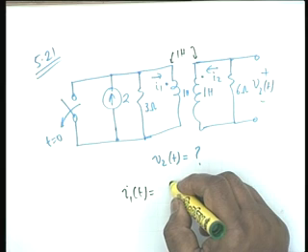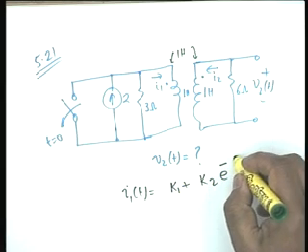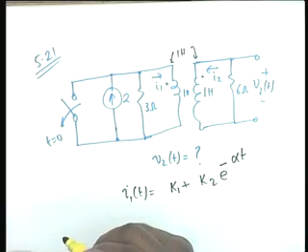But what do you think will be the order of the circuit? What order do you expect? I think we have done this, that if L1 L2 is equal to M squared, then it becomes a first order circuit. Okay. So if one asks you, without calculating anything, can you write the form of I1(t) and I2(t)? Obviously it will be of the form k1 plus k2 e to the power minus some constant, let us say alpha t. Agreed?